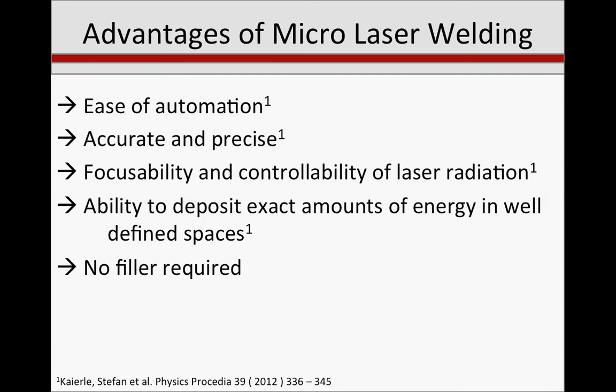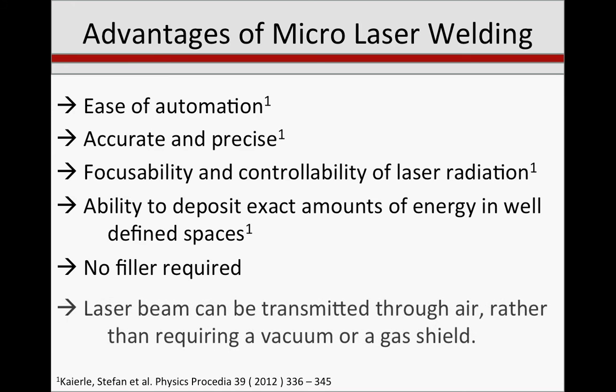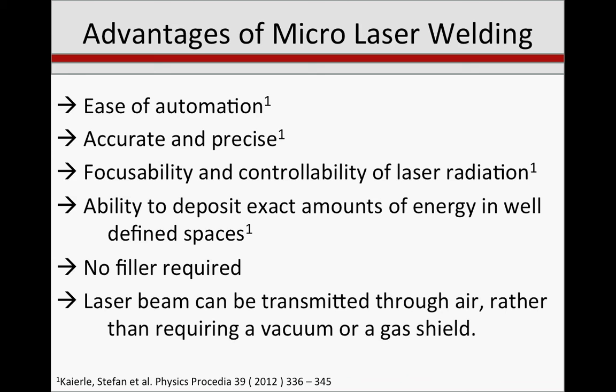One of the best advantages that it offers is that there's no filler material required, as is required with many other types of welding. The laser beam can also be transmitted through air without requiring a vacuum or a gas shield, reducing the complexity of the overall system.